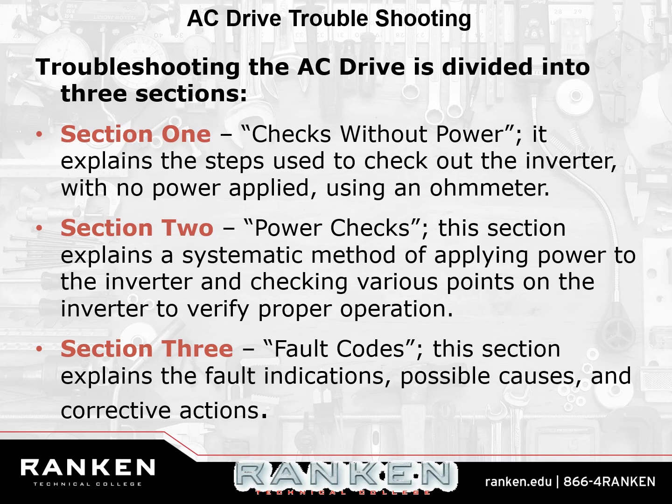Turn the power on and then check for voltage. Voltage, voltage, voltage. If you don't have fuel, if you don't have power, you're not going to go anywhere. And then check the fault codes. Checking the fault codes usually just explains what the fault condition was. Some of the newer drives will tell you more.